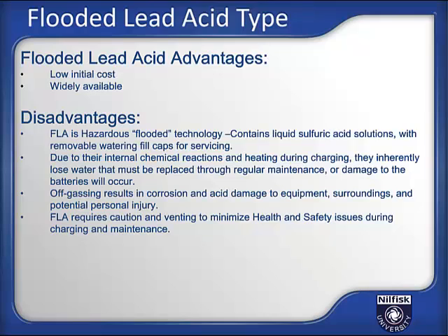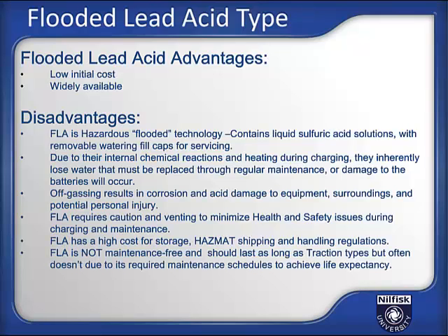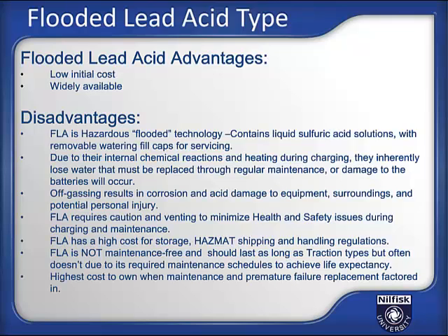Flooded lead acid requires caution and venting to minimize health and safety issues during charging and maintenance. And flooded lead acid has a high cost for storage, hazmat shipping, and handling regulations. Now, flooded lead acid is not maintenance-free, and it should last as long as a traction-type battery, but often doesn't due to its required maintenance schedules to achieve life expectancy. This technology has the highest cost to own when maintenance and premature failure replacement are factored in.